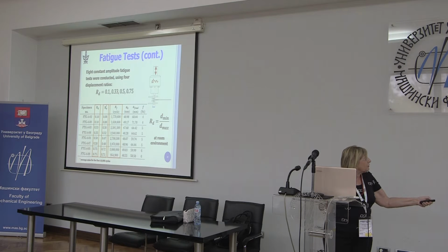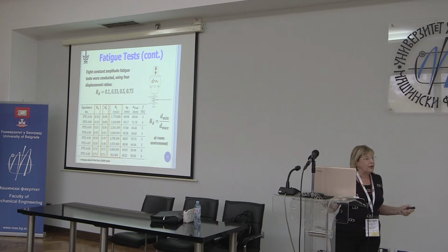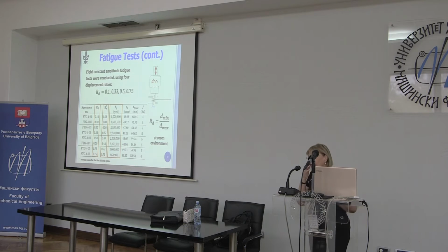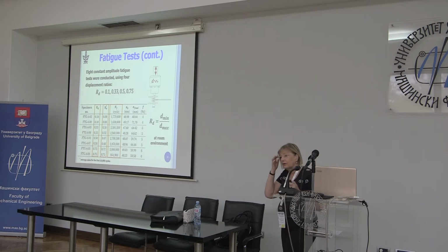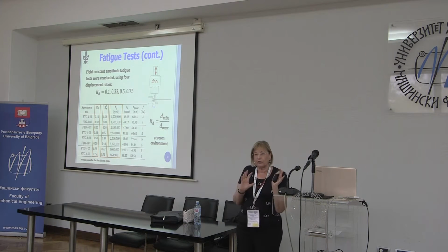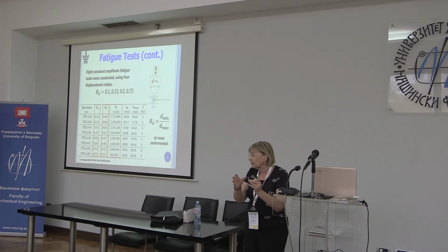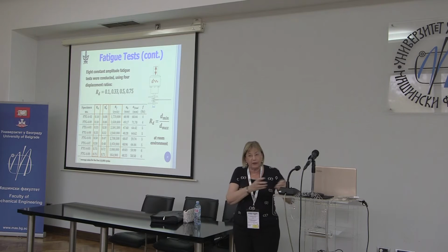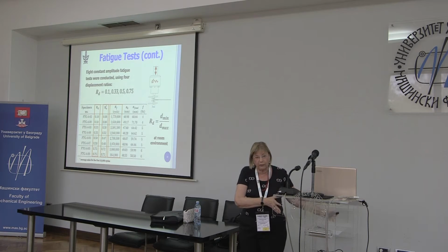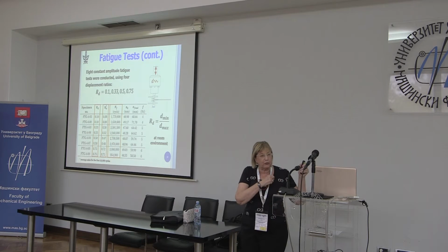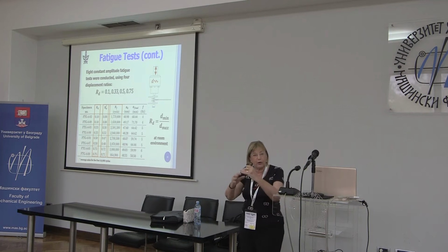And you can see the number of cycles that these will run. Our aim was to get to 3 million cycles, and we didn't always reach that. And when you run these tests, you have to run them 24 hours a day, 7 days a week. When we first started doing this, we have a paper where we ran them, and I said, okay, it's nighttime. Let's take the specimen out, put it in a container for maintaining temperature and relative humidity, and we'll come back tomorrow and we'll put it in.